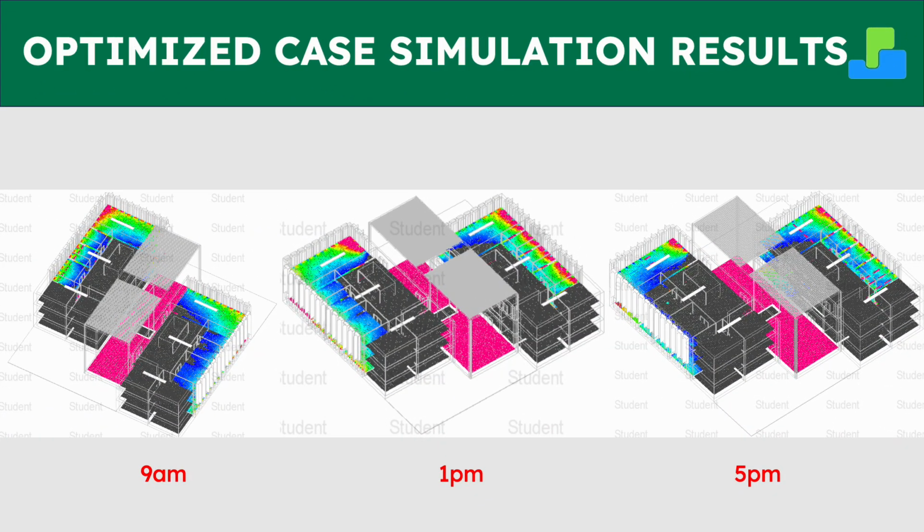The daylight factor and illuminance values have also improved with the implementation of the kinetic facade, which has allowed for a diffused light within the space, reaching the 2 to 5% daylight factor and 300 to 500 lux luminous intensity.